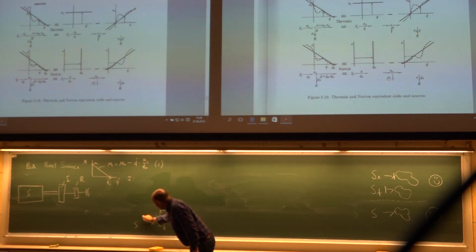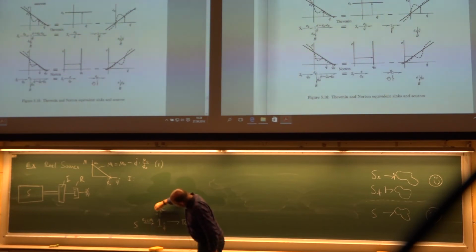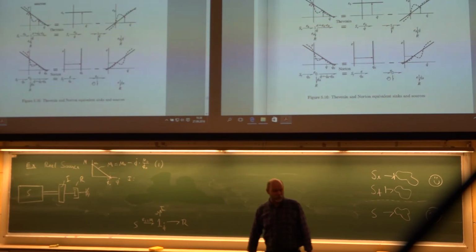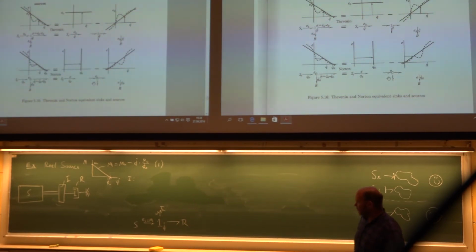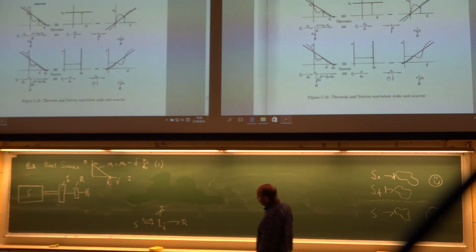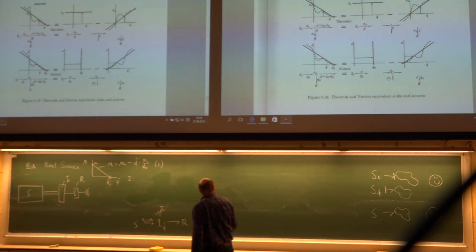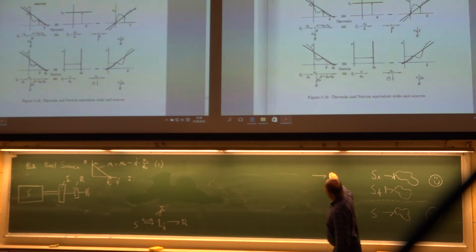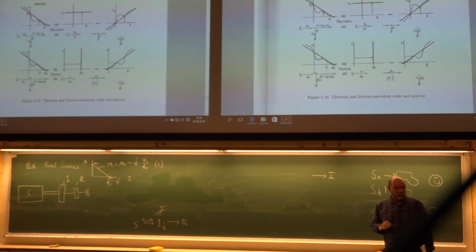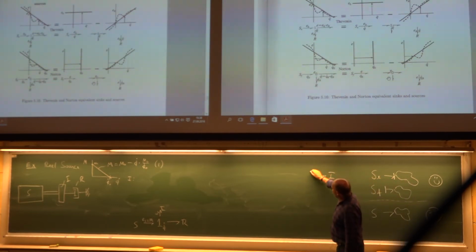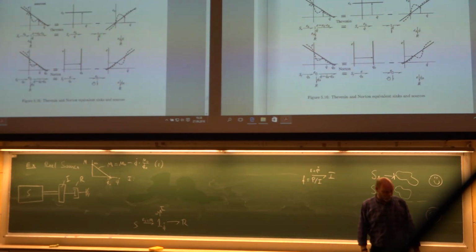Here you have an effort source equal the torque. Here you have an effort for the inertance. What's the effort for the inertance? Say you know the speed. How can you find the effort for the inertance? What was the rule for an inertance? Well, we would like to have the following. Effort equals P dot. And down here we would like the flow to be P over I. That was the flow, or Q dot if you like.